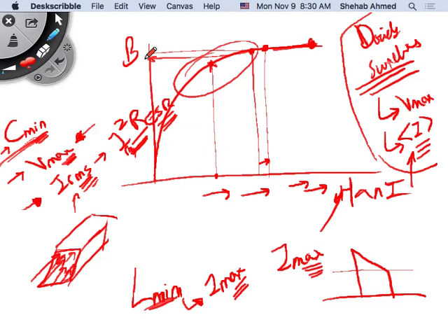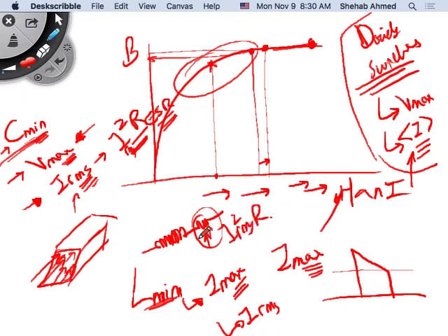Then there's another parameter, always related to heat. What is it? Again, inductor is a set of coils that have a certain resistance. So it's definitely the losses in this resistor. The losses in this resistor are dictated by the RMS current. Right? It's I squared R, sorry. IRMS squared times this resistance will dictate the heat in the inductor. Yes? No?